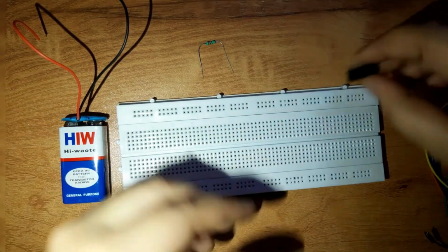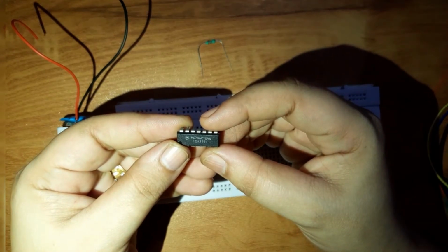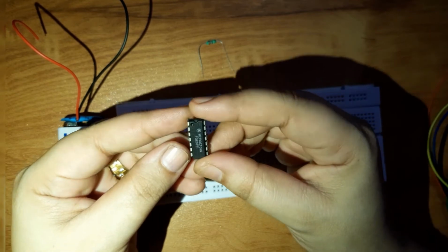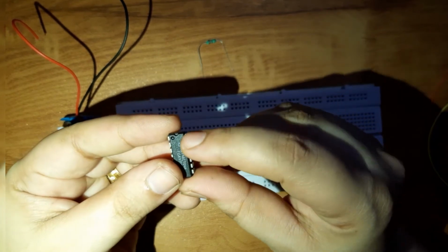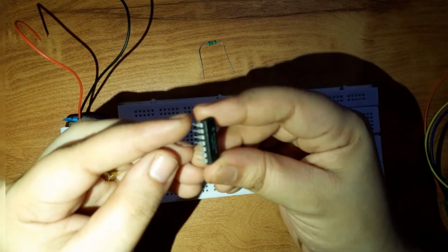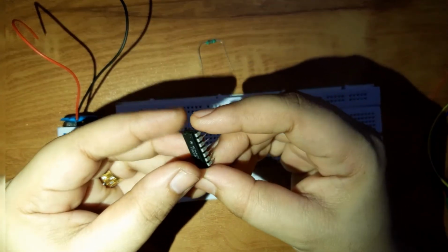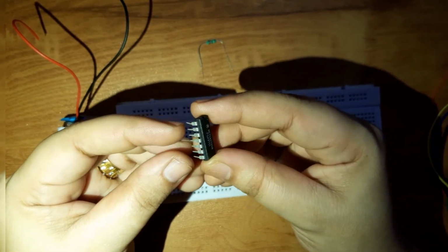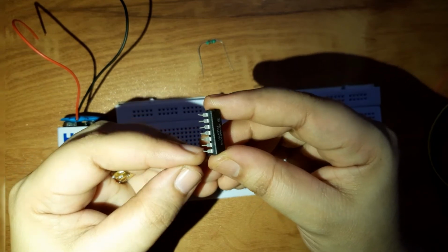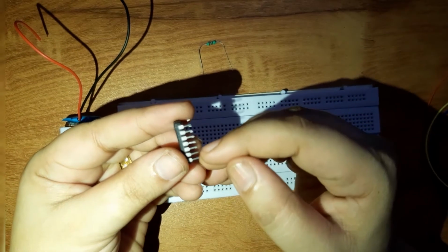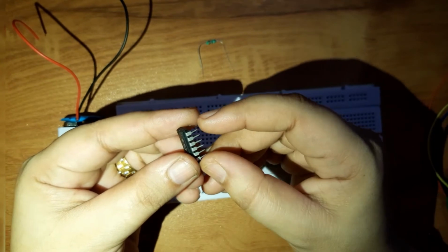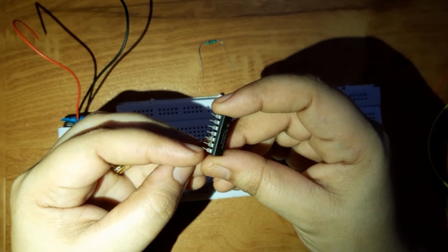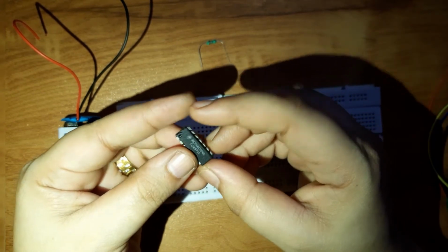Now this is the IC that I need for implementing NOT gate. This is 7404 IC. So if you hold up this IC like this, where this notch is on the upside, you'll find 7 pins on this left side and 7 pins on the right side. You can start counting these pins from here. This is pin number 1, 2 and the 7th pin, then pin number 8th, 9th and this way 14th pin. So this 14th pin is connected to the plus VCC and this 7th pin is to be connected to the ground. This is specifically for NOT gate.